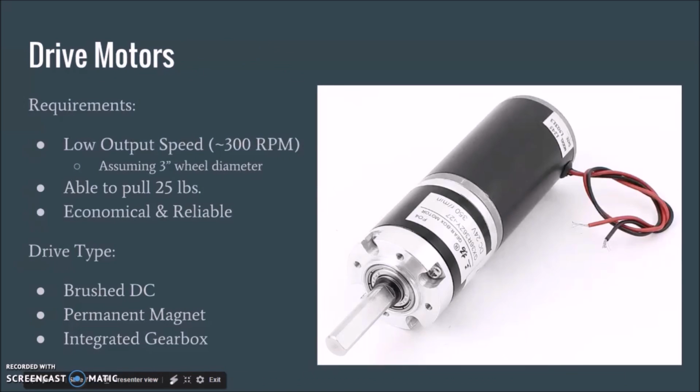We decided that the motor controllers should each drive a permanent magnet DC motor, each with an integrated gearbox on it. Permanent magnet motors are often used in small applications such as the Smart Luggage because they are compact and inexpensive to purchase. The integrated gearbox will allow the output shaft from the motor to spin very slowly and be connected directly to the wheel of the Smart Luggage. Also, because of precision machinery used in fabrication, the integrated gearbox will add reliability to the drivetrain.